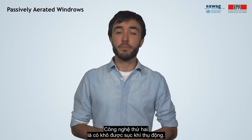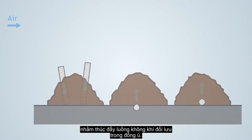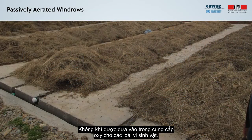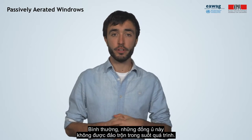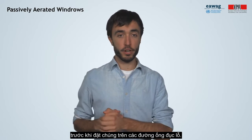The second technology is passively aerated windrows. This technology consists of perforated pipes located within the biowaste pile which promote convective airflow throughout the material. The pipes can be located in different dispositions as shown in the pictures. The air that gets into the pile brings the oxygen required by the microorganisms. These piles are normally not turned during the process. Therefore, it is important to premix the feedstock thoroughly before placing it on the perforated pipes.